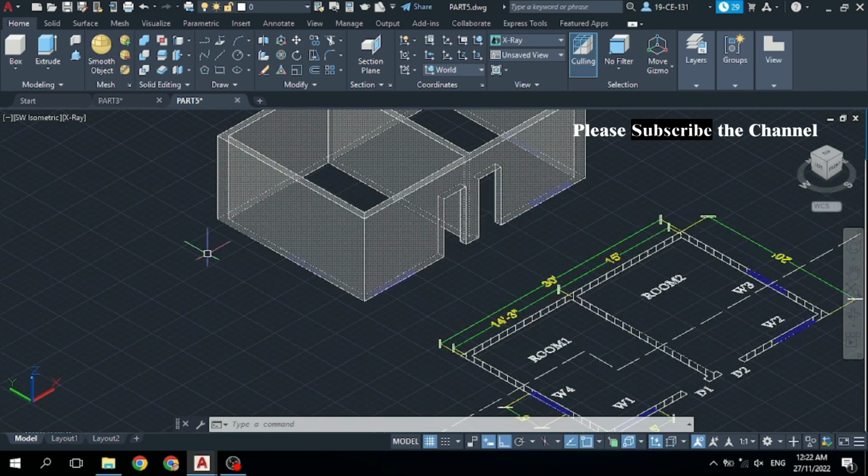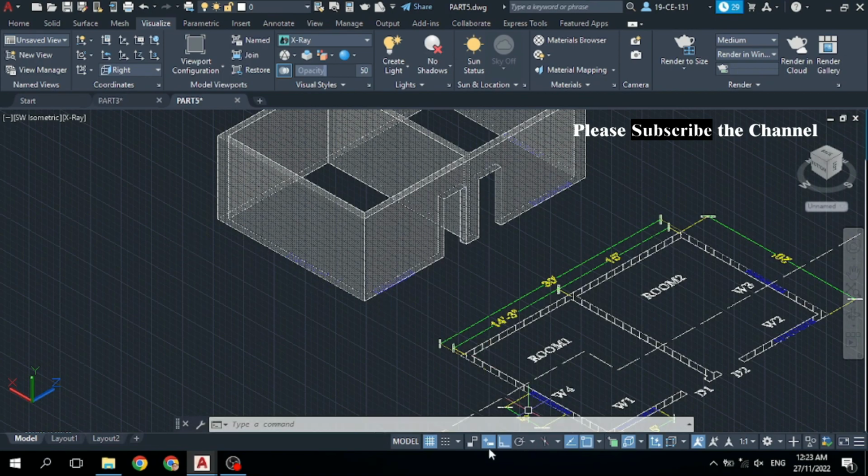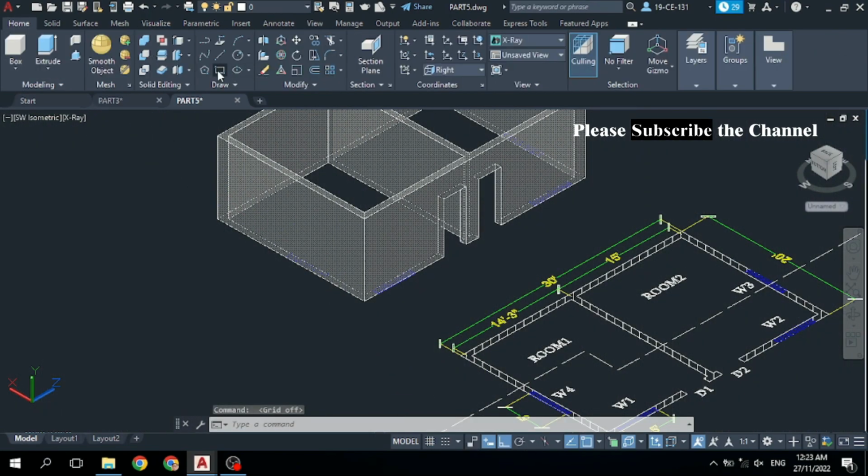So for that first of all come to Visualize and click this coordinate. It is very important. Most students make mistakes in this coordinate and then they cannot draw their 2D objects on different surfaces. So now I would like to be in the right page. Now you know that I am drawing in this page, so I would be in this right page, and after that come to Home and click on the Rectangle command.